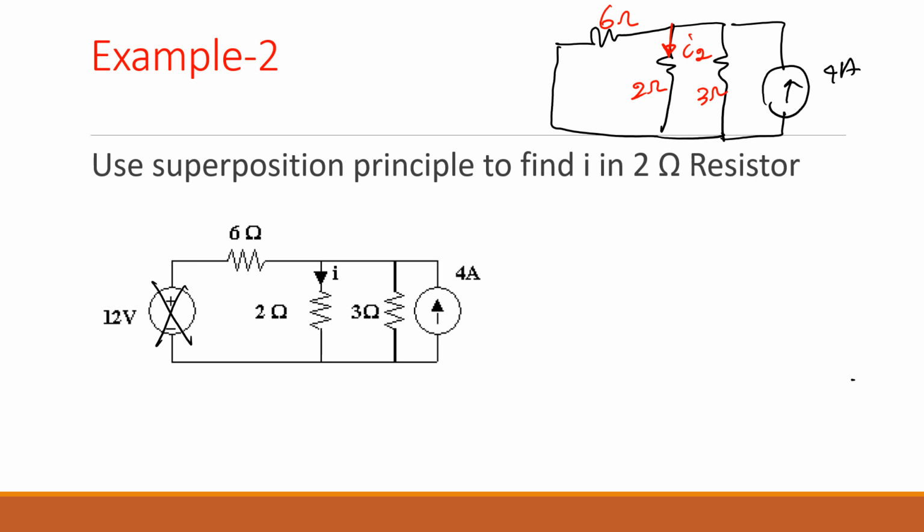These all three resistors are in series or parallel or what? They all are in parallel. So you can add them, but I'm going to add only two. I just keep this one because we need to find the current across that. But I can add these two because they are parallel with each other. All three are parallel, but we can just add two together.